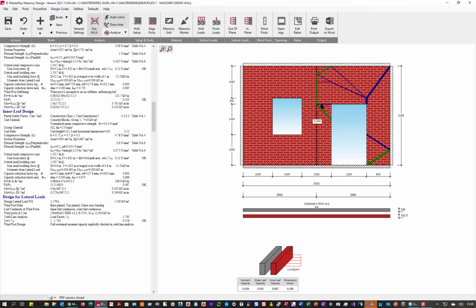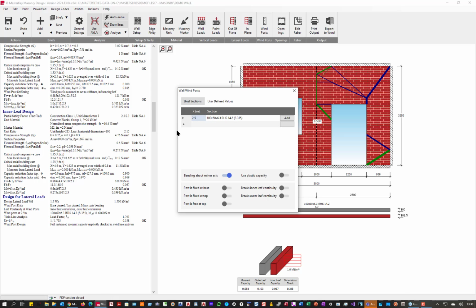So what I'm seeing here from this is that we're coming along down here with this vertical yield line. The green lines are what you would call hogging, and the blue ones are what you'd call sagging. So blue ones middle of the span, sagging. Green ones at supports. And you'll see that it's acting as a support because the yield line is running along the member.